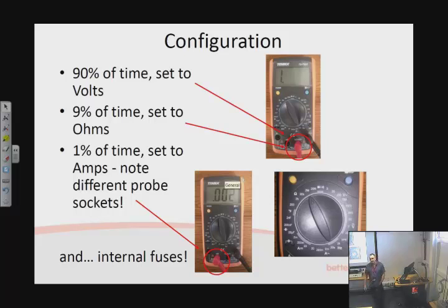They also come with internal fuses, so if the thing's died, that's the first thing you should check. The second thing, after checking that the sockets are correctly configured, check the internal fuses before you throw the thing in the bin. But yeah, nice, all sorts of different ranges that these devices work on, and different quantities that they can measure.